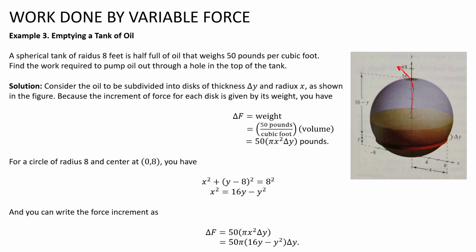Okay, take note that the weight is in pounds per cubic foot. So this one is force per volume, right? You need to multiply this with a certain volume for you to be able to determine the total force. If you don't know the volume of the sphere, since our problem is about the sphere, you need to determine the volume of the sphere.